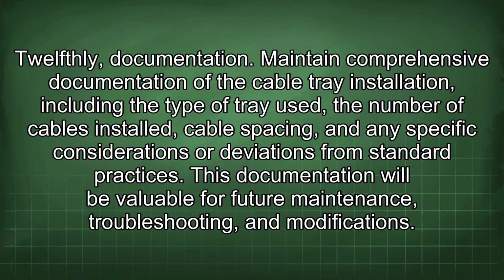Twelfthly, documentation. Maintain comprehensive documentation of the cable tray installation, including the type of tray used, the number of cables installed, cable spacing, and any specific considerations or deviations from standard practices. This documentation will be valuable for future maintenance, troubleshooting, and modifications.